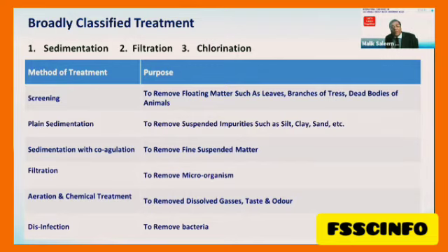advanced technologies. We can also go with ultrafiltration, which requires far less area and far less time for setting up the project, and its reliability is higher than the conventional sedimentation system, because you need to have the proper dosing, jar testing, control the parameters, sludge handling, and a lot of other things you have to manage to control the process.